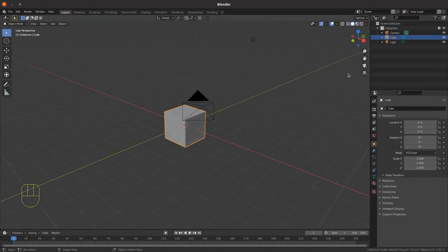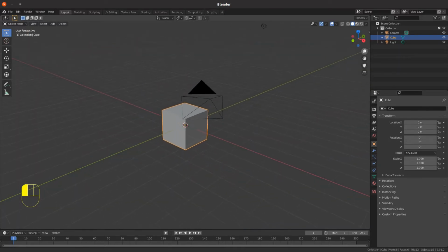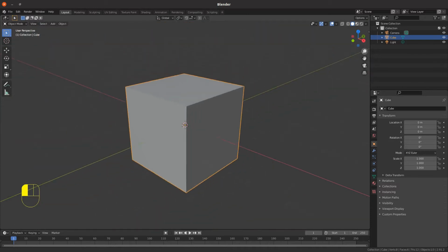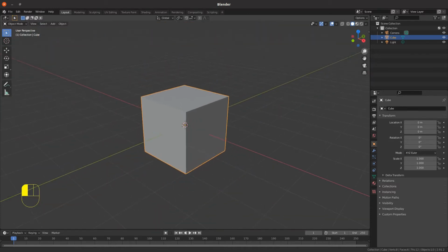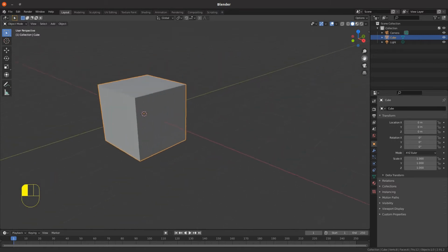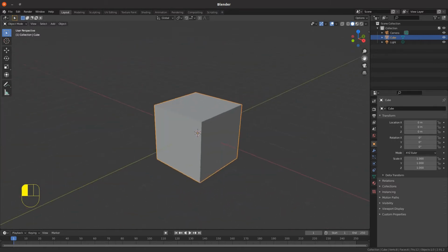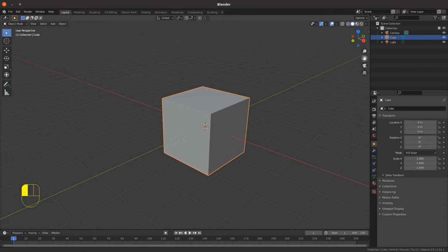And then below that we've got the zoom option, and you simply click on that icon, and while your mouse is over the icon, once you click and drag with the left mouse button you can zoom out or zoom in, and it acts directly on the centre of the viewport, so that's the centre point of all these tools. The move icon just allows you to pan the 3D objects around the screen, or take them out of view completely if you wish to, or even over onto another screen.